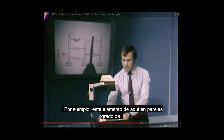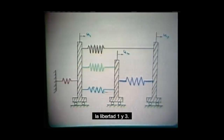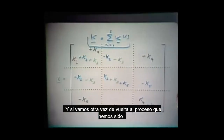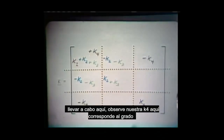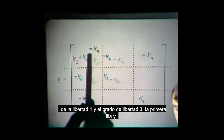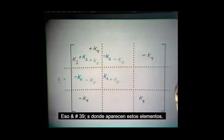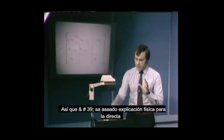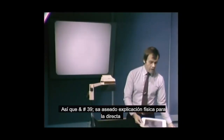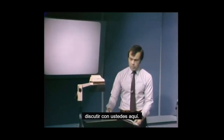and adding them into the appropriate columns and rows of the K matrix. For example, this element here couples into degree of freedom 1 and 3, and if we go once more back to the process that we have been carrying out here, notice our K4 here corresponds to degree of freedom 1 and degree of freedom 3. The first row and column and third row and column. That's where these elements appear. So there's a neat physical explanation for the direct stiffness method, which I wanted to discuss with you here.